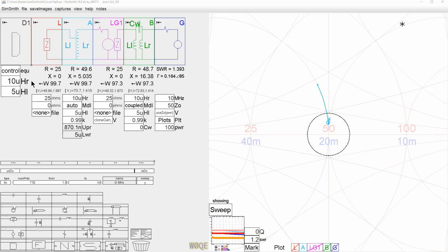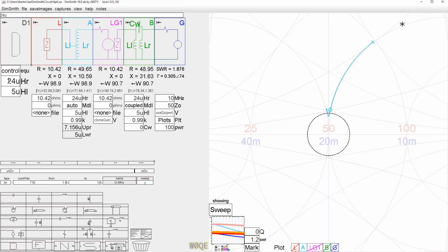Well, I can do it. I'll do it for the purposes of just doing it, but you don't want to do it just willy-nilly, because what we're going to see is, okay, now we've made the low frequency performance good, and high frequency performance isn't as good in this auto transformer. This is a lot more turns. If we need more turns on a transformer, maybe that's okay, but generally fewer turns is better a lot of times. And the auto transformer, while it's okay.